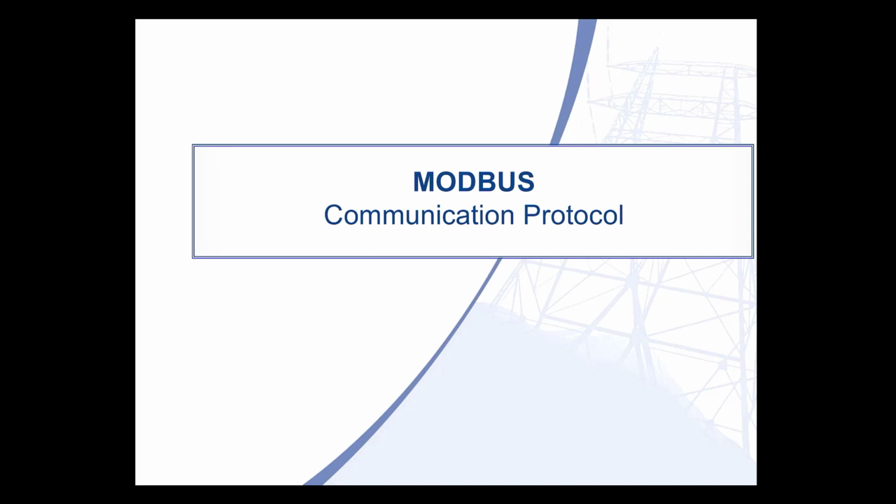Back in the day, when it was owned by Modicon, all of the addresses for the different data types, whether DIs, DOs, analog inputs, or analog outputs, had specific register or memory locations that were the same from one device to another, all dictated by Modicon. But now that can all be changed, tweaked, or specifically configured for your own purposes.